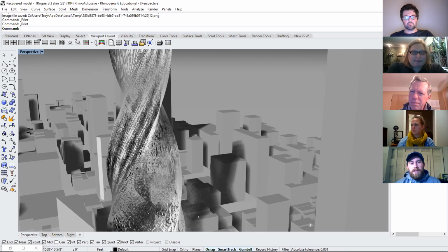But if you're going to do this kind of perforated shade, typically what works best from my experience is you do it all two-dimensional, and you don't ever actually apply it to the building geometry. You make a map of it and then just use it in the rendering, because the amount of geometry involved in applying it to a gigantic tower is insane.